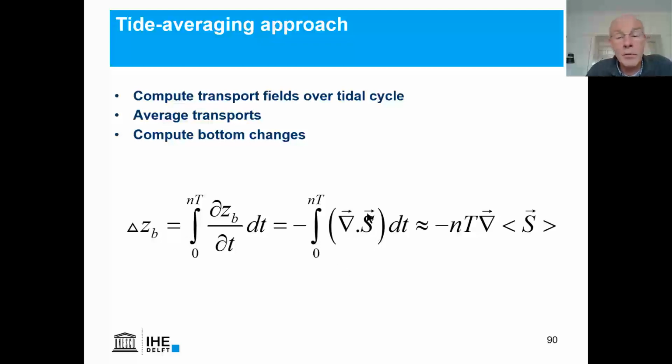So far, no real approximations are made, but what we need to consider is that the sediment transport varies as a function of the tidal forcing and wave forcing, but also because in the meantime the bottom changes. So between 0 and N tidal cycles, the bottom is going to change.